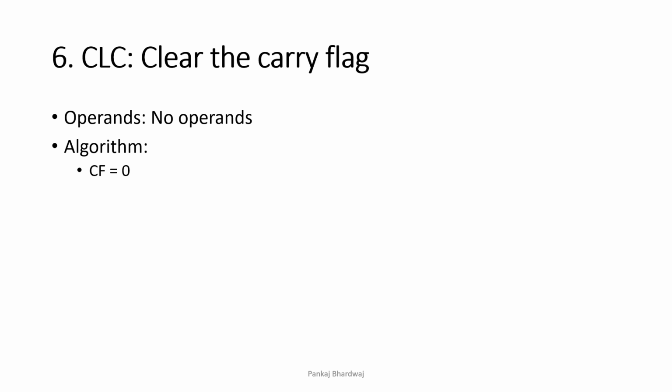Next is CLC, clear the carry flag. That means whatever the value of the carry flag, after this operation CLC, the carry flag will become 0. If it was previously 1, then it will become 0, and if it was 0, then it will also remain 0. So it simply clears the carry flag, nothing else.